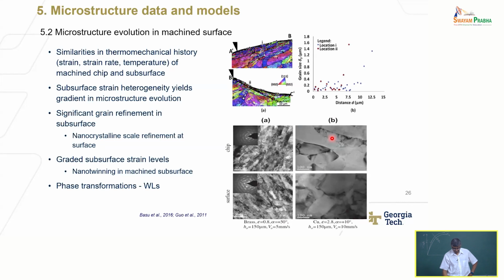We're not there yet. Because you can produce nanocrystalline grain structures, very highly refined grain structures, using machining. Simple machining, right? You produce nanoscale grain structures, extremely high hardnesses, etc. Which can be a good thing, but doing it experimentally versus being able to model it, that's still a challenge. People have done it experimentally and shown it.